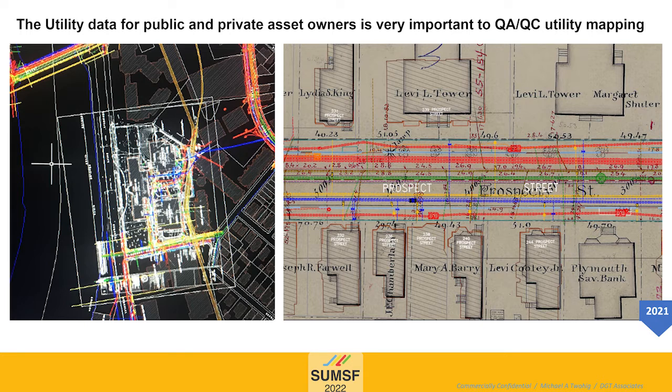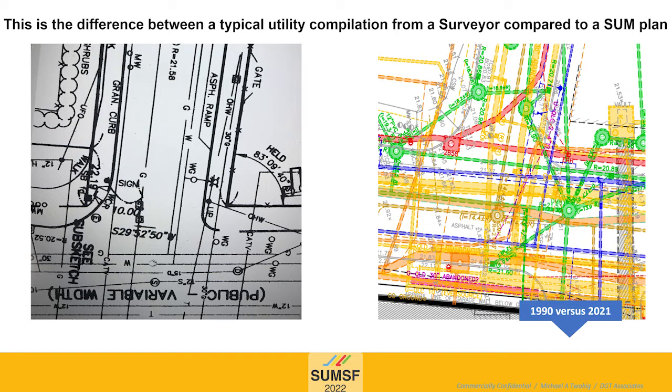And of course, with many organizations looking at how to minimize crossbores because of directional drilling, if you look at the old legacy documents, they showed us the way where they surveyed the existing infrastructure, they plotted it, and today we XREF these documents in to become very reliable for our work. And this is the difference between a typical survey done for other purposes on the left, and on the right side, we're looking at a documentation for the same street 20 years later, but we're actually adding in all the subsurface information we get from our remote sensing.